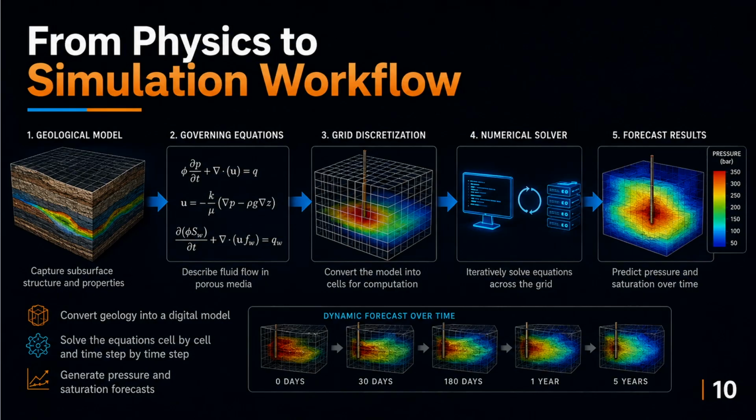First, we build a geological model. Second, we define the governing equations. Third, we divide the reservoir into grid cells. Fourth, we solve the equations numerically. Finally, we generate forecasts of pressure, saturation, production, injection, or storage behavior.